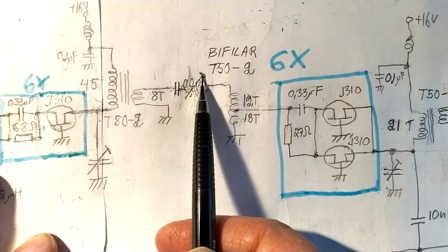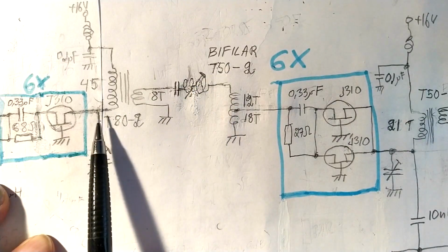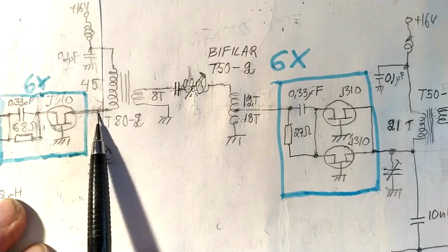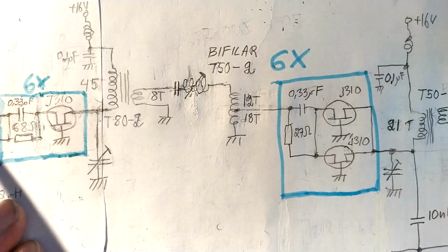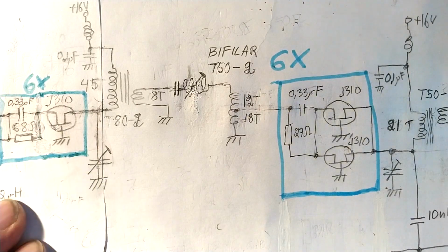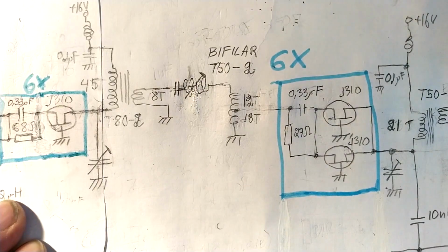It means set this inductor for lowest possible impedance in this point, because that gives the best possible loaded Q for the crystal. And the way to tune it, look with the network analyzer and measure the Q and adjust the screw on the trimmable inductor and look what happens to the Q, and there is an optimum for a certain position.